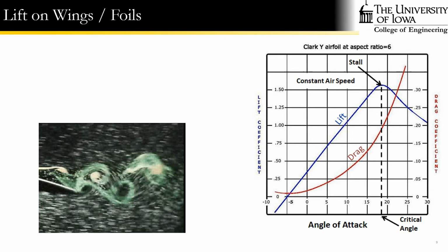So that's why the conventional wisdom is, for pilots, if your wing stalls out, you're supposed to go into a dive, right? You're supposed to try to decrease your angle of attack down into the region where the flow is reattached and you regain control.